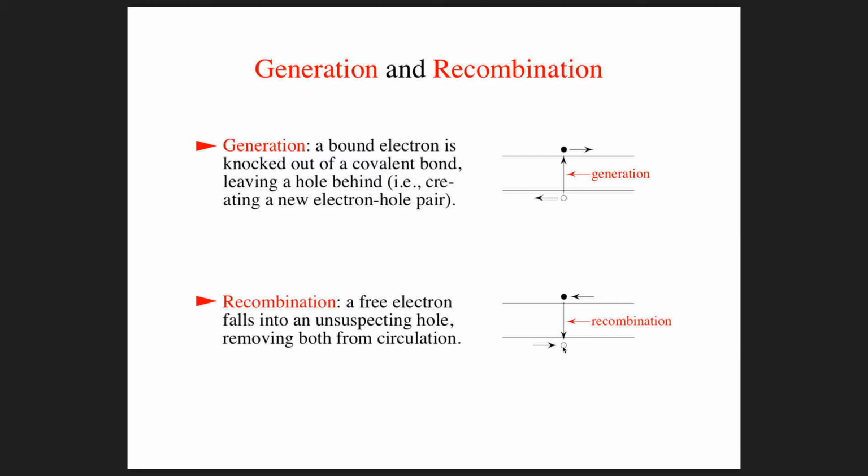So while silicon is very good at absorbing light, you can easily make a photodiode or a phototransistor out of silicon and absorb light and get an electrical signal that's proportional to the rate of photon absorption in a given area. It's actually hard to make silicon emit light efficiently. That has to do with something called the direct band gap structure versus an indirect band gap structure. III-V semiconductors have a direct band gap structure where this kind of emission of an optical photon is very likely. Silicon has an indirect band gap structure, which makes that much more unlikely. And so what happens to conserve energy in that case is that you have a lattice vibration, sometimes called a phonon, which is sort of a sound wave particle thing, propagate from this event in silicon.